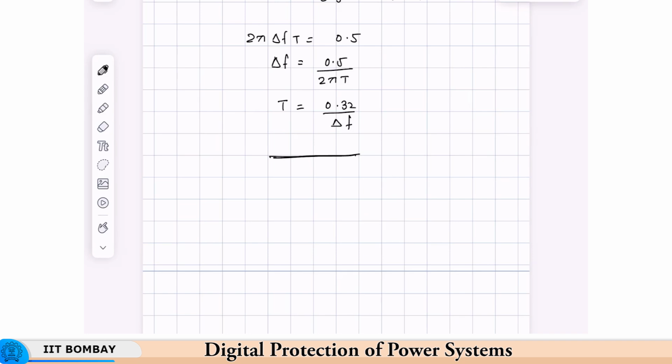The voltage, on the other hand, does not have so much pollution with other frequencies, and it is there irrespective of the load. The voltage is usually held in a very narrow band. So that is why for calculation of frequency, voltage signals are preferred.